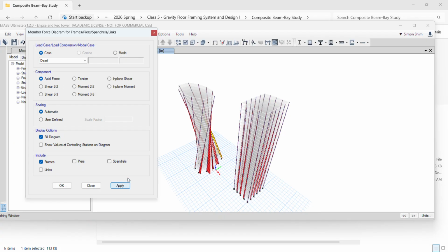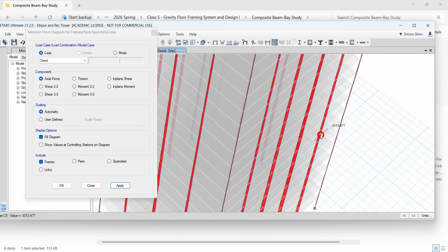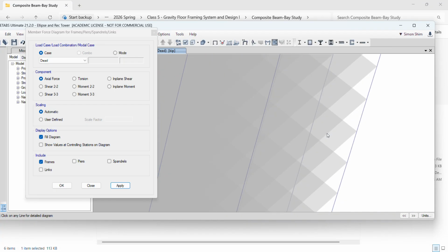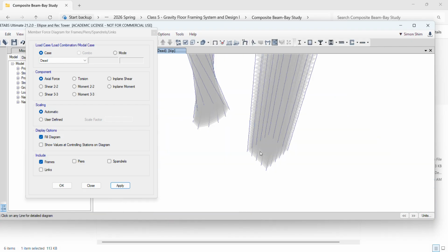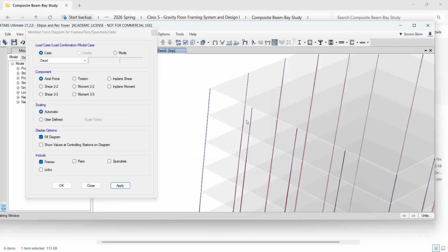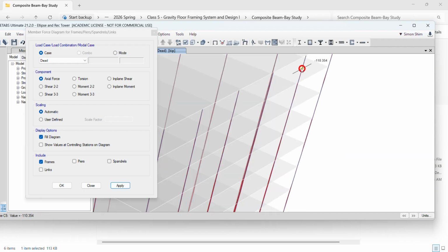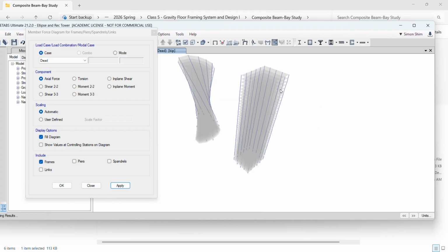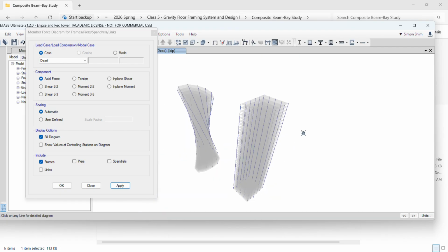Your guess is straightforward, a no-brainer, right? The column should experience compression. Here everything is vertical. Red color means compression forces. Since it's in kips, wow, 3,000 kips. Yeah, this is with an 8-inch slab. Obviously at the top the actual compression force is small, but as it goes down, you see that the columns are taking more forces. It's common sense.